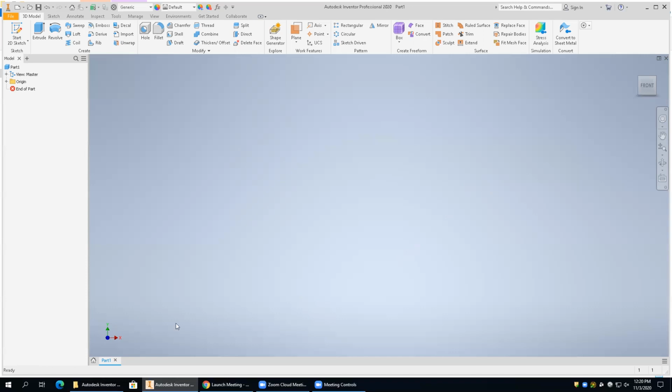You have a view cube over here. There's your view cube. The view cube is going to manipulate you and move you around in 3D space. So that's going to be something we'll be working quite a bit with. You do have help menus down here that'll show you information. So that's the closest thing you have to the command window in AutoCAD. Okay, so it's going to give you information. And that's called your message or single line help indicator. And it does give you some information. I don't use that as much as I probably should. So you might want to keep focused on that a little bit as you get started into these modeling processes.